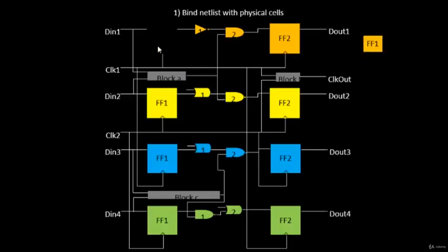So for example, you have this flip-flop, which is a square shape over here. It's actually a box of square or rectangle shape. For example, you have this NOT gate, which is some triangle and a circle over here, but in reality it's a box. It has got some physical dimension. It has got a width and height of this particular cell.